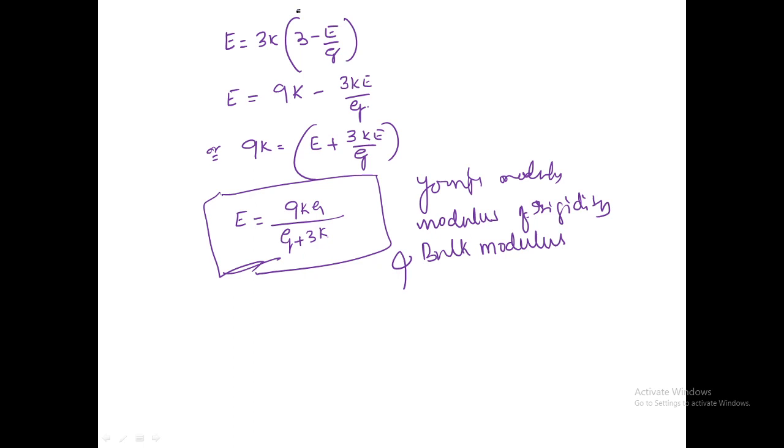You may get confused while writing the equation for strains: one because of the tensile strain along the diagonal BD, and another strain because of compression on the opposite diagonal. Because of the shear stress, you get a tensile strain. If you practice, you will get this relation.